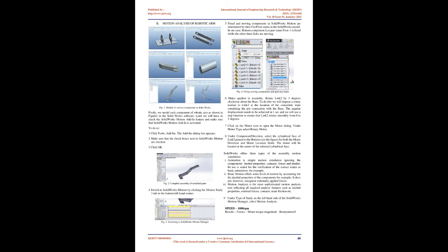6. A representation of the DH forward and inverse matrix is obtained generally. An analytical solution for the forward and inverse kinematics of a 5DOF robotic arm is presented, to study the movement of the arm from one point in space to a different point. The 5DOF robotic arm is a vertical articulated robot, with 5 revolute joints.